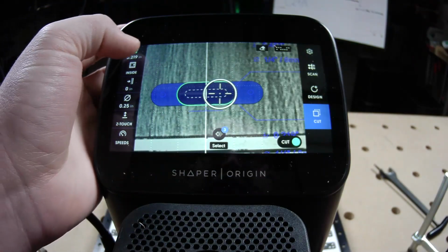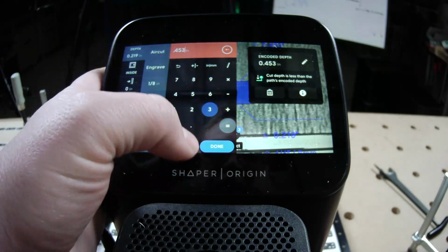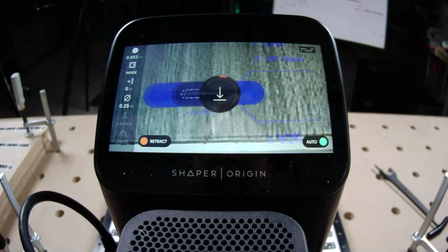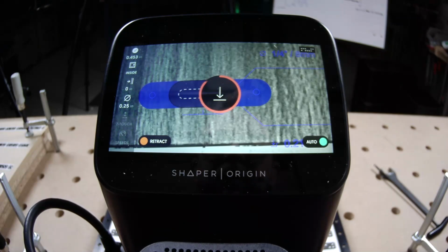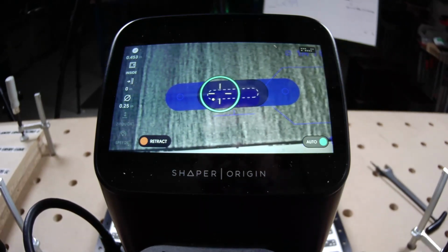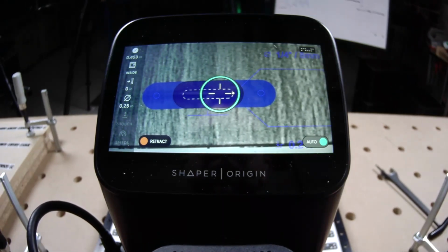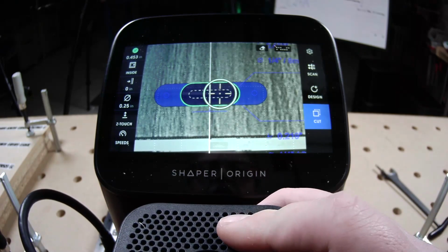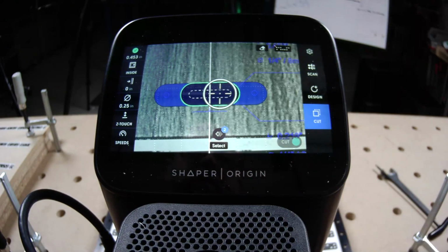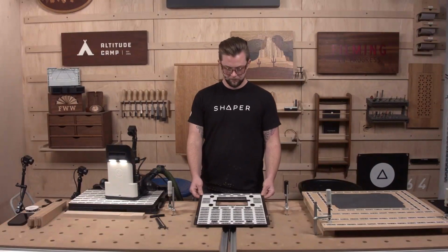You can go right back to that workspace, and all of your templates are completely saved, and you're ready to use them at absolutely any time. So where that's really handy is setting and editing the encoded depth on tool. That's going to save with your workspace, and so anytime you go back to that workspace, those encoded depths will still be there.